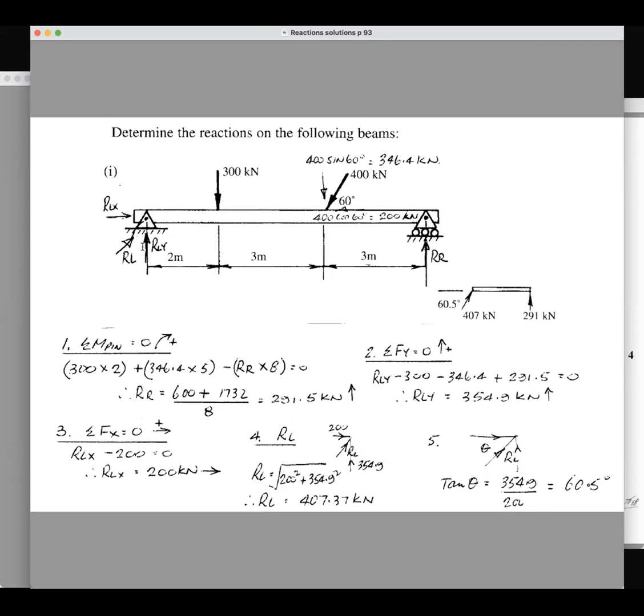Now, if you put the vertical reaction here, which is going up, which opposes those 2 external forces acting down, and your horizontal reaction at this pin to resist the horizontal component of this inclined force here, the examiner will see that you know quite a bit about the reactions at a pin, and you'll get marks for it.